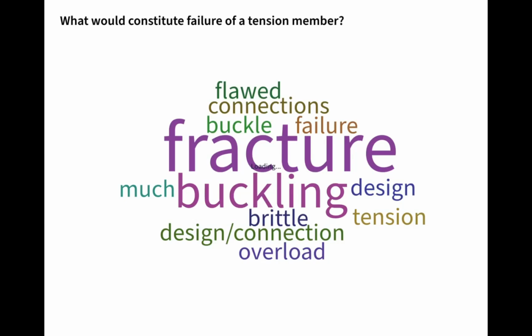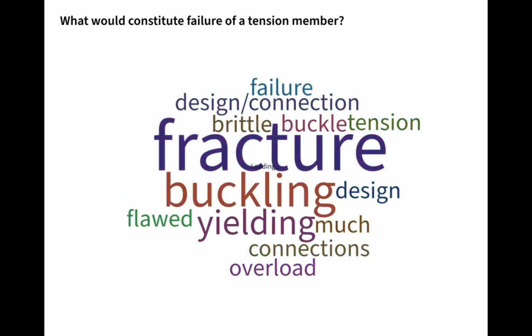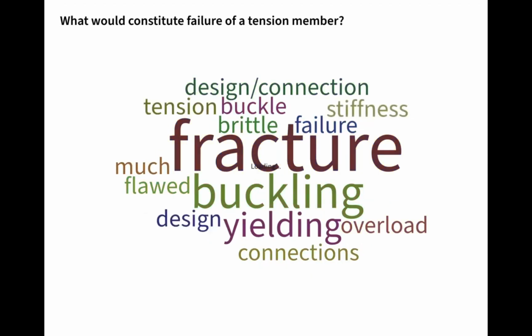I don't see yielding here anywhere. We're going to see that yielding of our braces tends to be a ductile mechanism. It means we're going to see a lot of movement in our structure before we actually get collapse developing in the building, which can provide warning for people in the building to get out. And so we're not as worried. Well, of course, we're always worried about failure, but we're more worried about brittle failure.